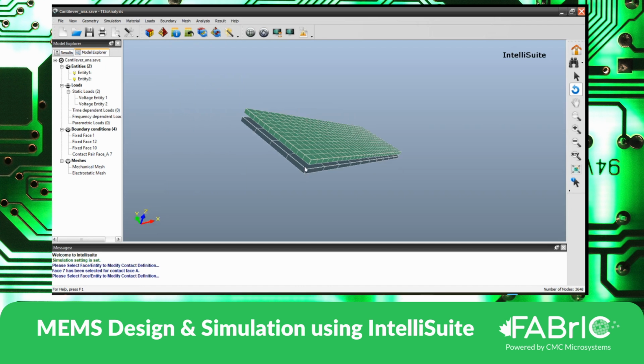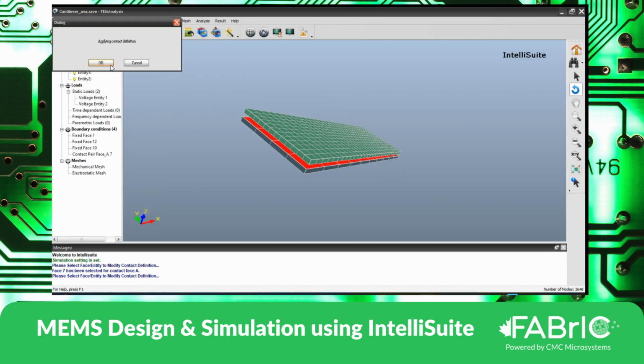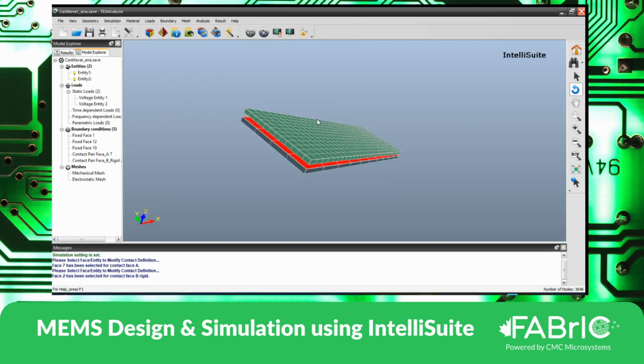So when I define this, assume that I'm applying the voltage 0 to 100 and the pull-in point, or the touching snap-down point, is at 70 volts. Then when the geometry gets to know that it has touched the bottom and it cannot go beyond that, the simulation converges there and the results are produced.